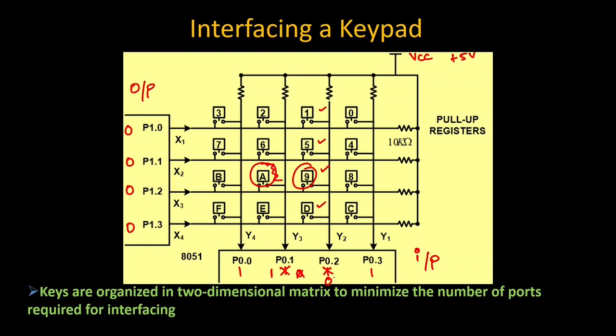So if I am not going to press it, the value of 5 will be directly reaching here. If I am going to press it, this is going to be short circuited, so the value of 5 volt is not going to reach here, and at the final output we are going to get the value of 0 here, right?